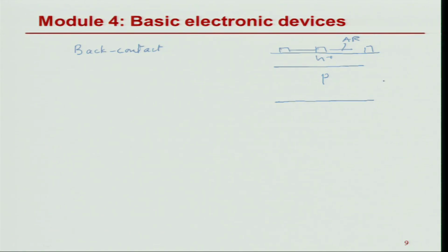On the back side, now I repeat this process, but not for N plus, but to get the P plus. And for that I can use gases like boron bromide or even diborane. Those can be used to oxidize the surface and introduce additional p-type doping. And finally, I will use silver aluminum paste for making the back contact.